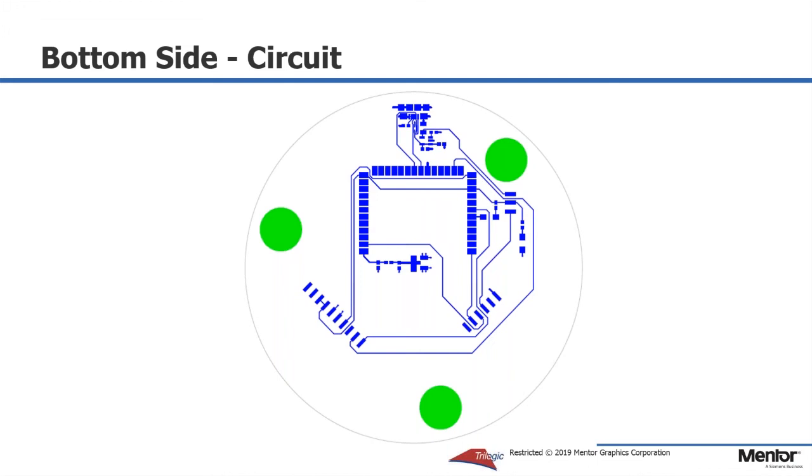So very little attention, you'll notice, was given to the power and digital portion here. You can see this is really not an ideal way to lay out a board. We did it on purpose to make a point. I can't remember if we auto-routed this or just very haphazardly routed it, but we really just wanted to stress how important it is on a design like this to pay most attention to the RF portion and the matching portion of the design.